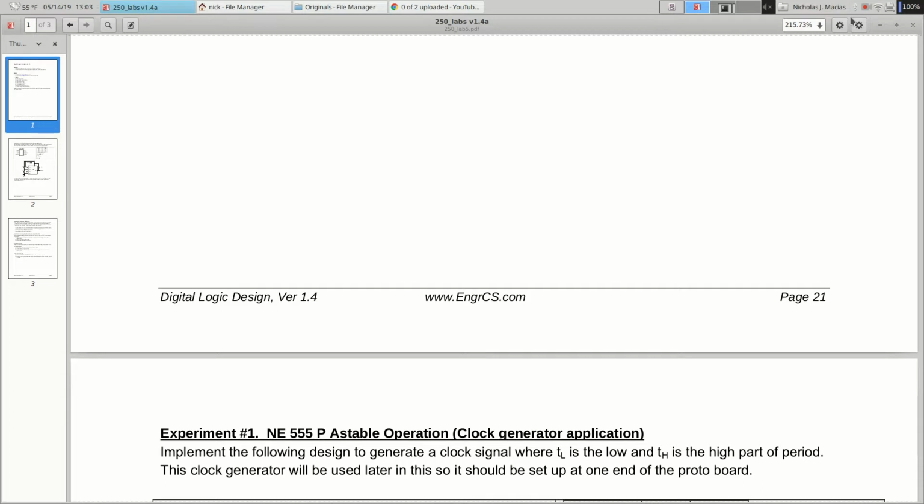What would be the difference between a fuse map and a printed circuit, and what applications are they used for? Fuse maps are only used for dealing with programmable devices. A programmable device is basically a generic piece of hardware that we can customize to do whatever we want, and so you blow certain fuses to make certain connections and implement a circuit like that.